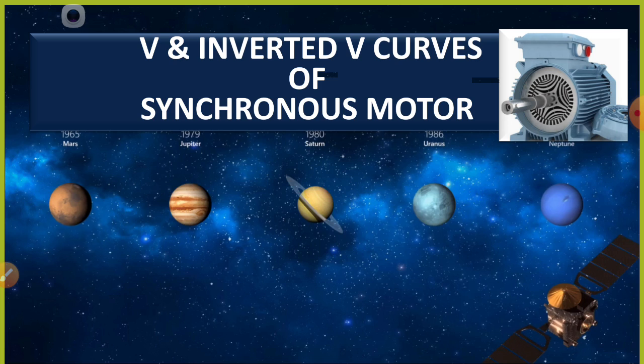Then, first case, the prime mover power developed in the motor is equal to EB into V by ZA cos theta minus alpha, minus EB square by ZA cos theta, where alpha is the load angle, theta is the internal angle, and phi is the power factor.